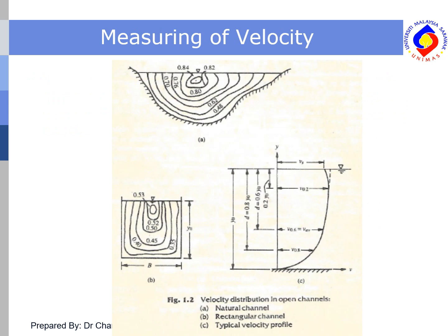This slide shows the velocity profile, or the velocity distribution, vertically in the flow depth. As can be seen in Figure 1.2c, the velocity profile is distributed following a logarithmic manner. Even though, as we have seen in the previous slide, the maximum velocity occurs just below the free surface, to ease our calculation we normally assume that the velocity is logarithmically distributed.